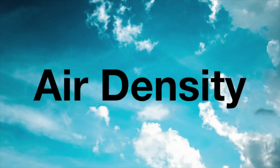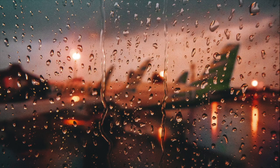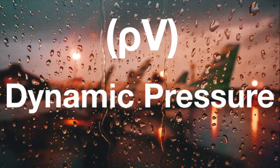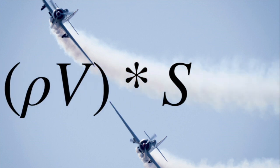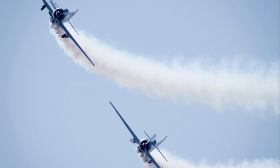Rho represents air density. The greater the air density, the greater the lift produced. This is because there are more air molecules in denser areas, and so more molecules will be striking the airfoil. The true airspeed of the aircraft is denoted by V. By grouping rho and V in brackets, their product is known as dynamic pressure. Pressure, as we know, is measured in force per unit area. Therefore, if we multiply the dynamic pressure by the area of the wing, S, we will obtain the force generated in newtons. Thus, we can then calculate the force required for a successful flight.